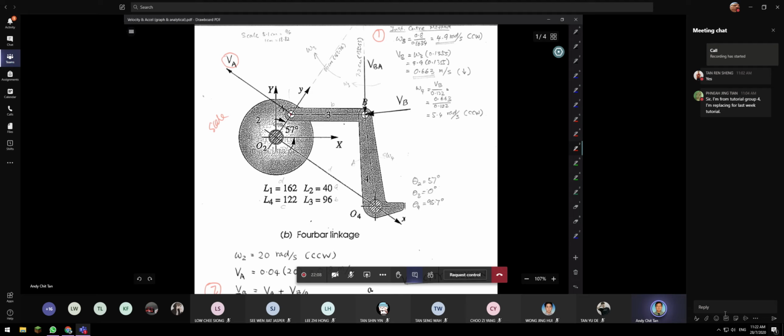Okay, perpendicular to the radius. Therefore, you can construct this line here. Now, acceleration of B is also perpendicular to this link. Therefore, you can construct this link here, perpendicular, along here. Now it's out of the paper here, so I just extend it.